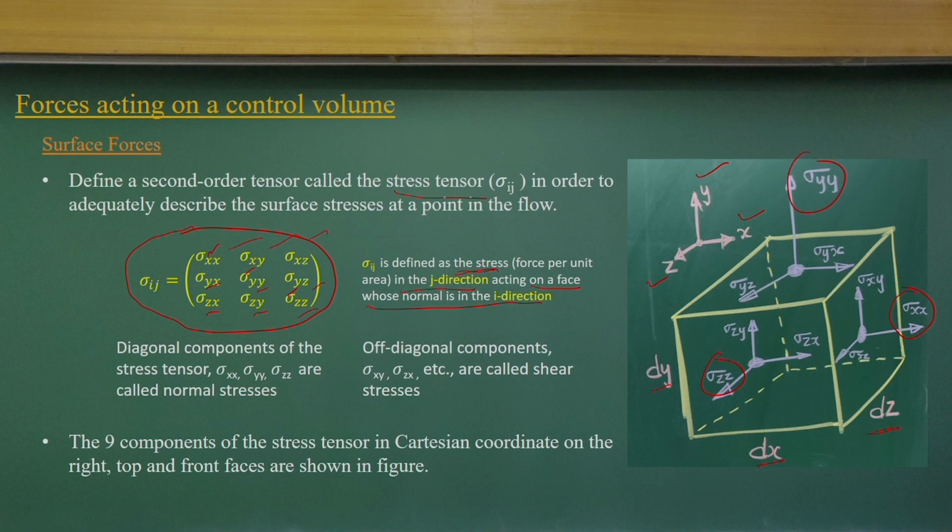These are compositions of the pressure force and the viscous force components. The off-diagonal components, sigma xy, sigma xz and so on, act tangentially. So basically these are the viscous terms. Over the surface we can define either the shear stress components or the viscous stress components.